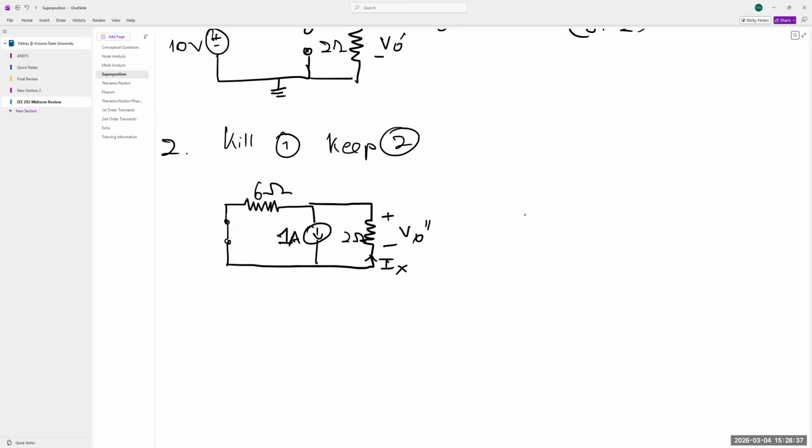All right. So the solution to the circuit is fairly easy. First, we can find Ix using a current divider. Ix is equal to 1 amp times the opposite resistance over the sum of the resistors. So Ix is 6 over 8 amps. Okay, now let's try to find what the voltage drop across the 2 ohm resistor is. So the current's entering over here and exiting, it always needs to exit from the negative terminal.